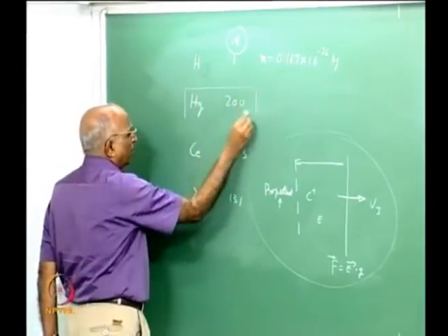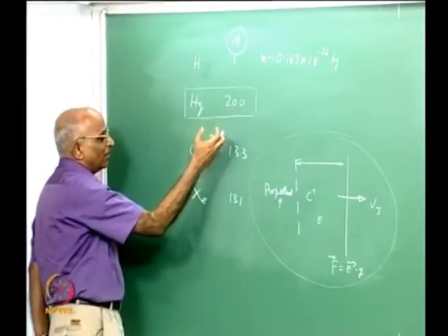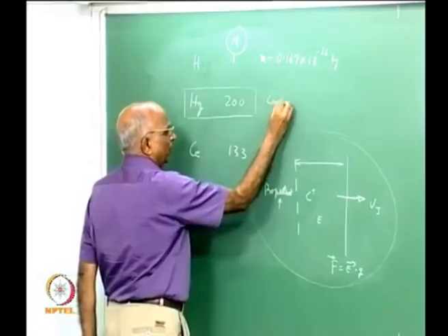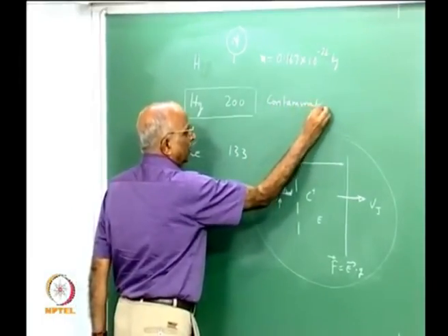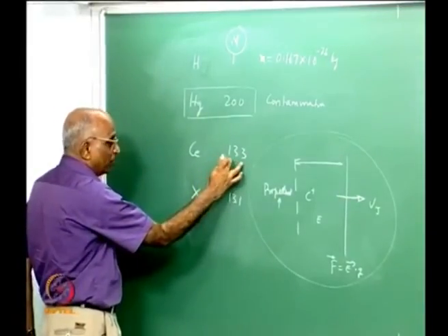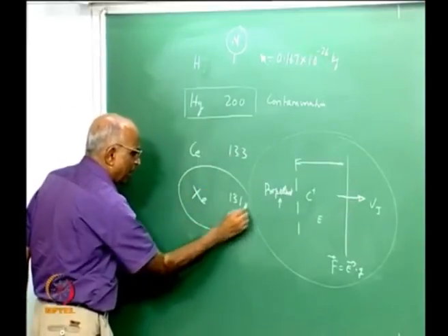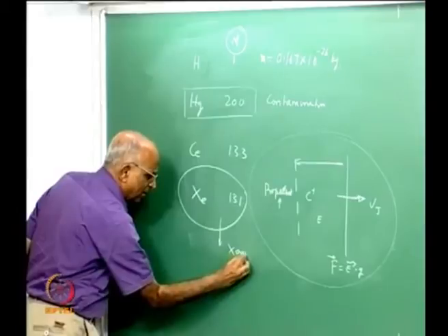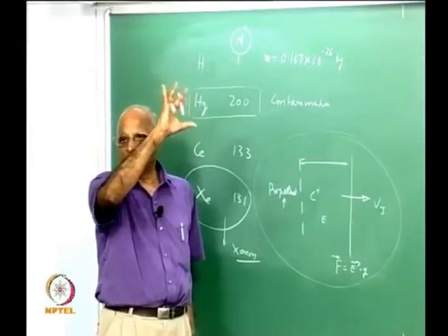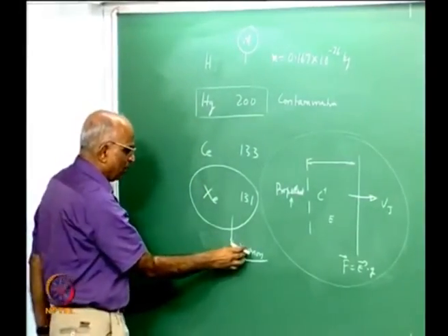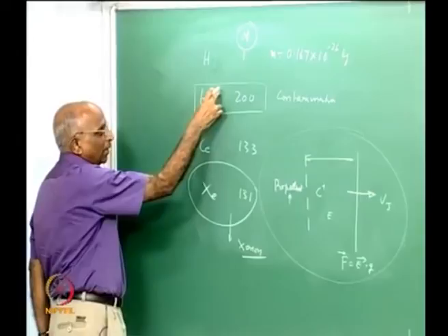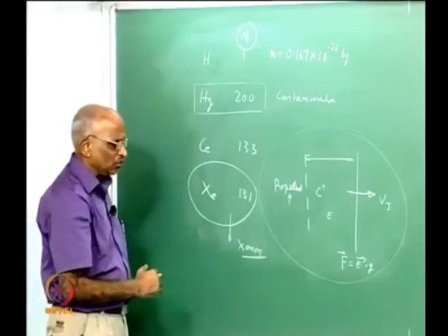Mercury is a liquid metal, but its vapor is dense, and when it is used in spacecraft it coats the surfaces of the spacecraft and causes contamination, whereas cesium is a little reactive, even though it can be easily ionized, and it is more difficult to use. The general trend today is to use xenon, which is a noble gas. Where do we use xenon in real life? Maybe we see these hoardings which have some colorful display, that is noble gas xenon. Therefore we use xenon as a propellant, but cesium is also used, and in the older electrical propulsion systems mercury is also used.